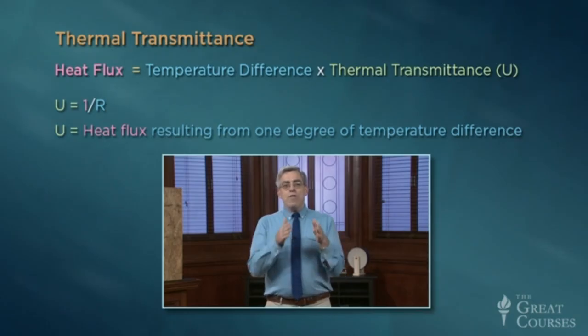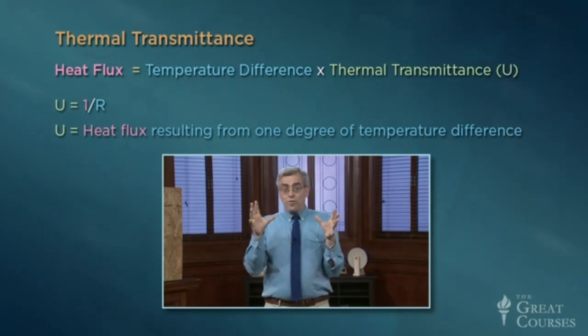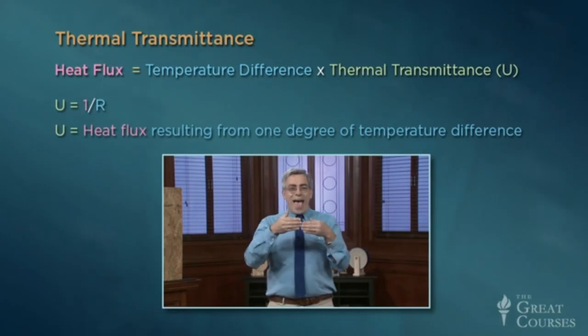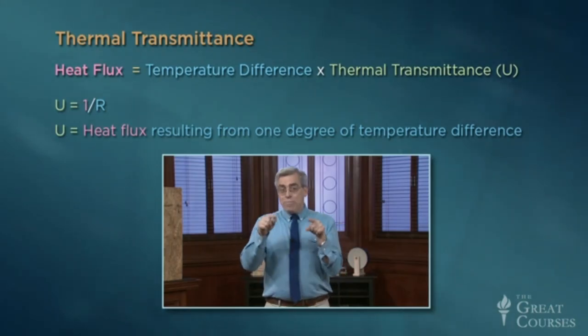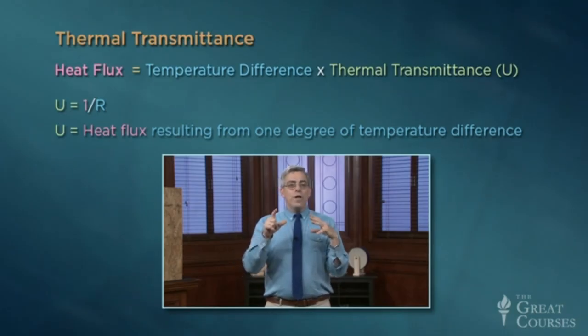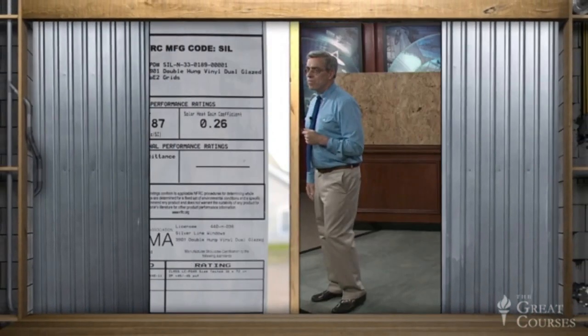As we've seen, the thermal resistance is additive. The effective thermal resistance of a wall can be calculated by adding together the R values of its individual layers. This cannot be done with a U factor. So it really does make sense to use R for insulation calculations.